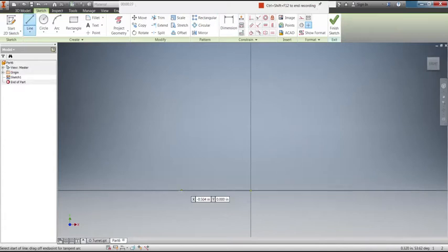And I'm going to draw the straight lines and then add some dimensions. We're going to be doing a revolve, which is going to be making this. This is basically cut in half, and I'm going to put a curve here in a minute. And this is what it would look like as half of the half. And this center line here, this is going to be the center of the piece, and it's going to be revolved around.